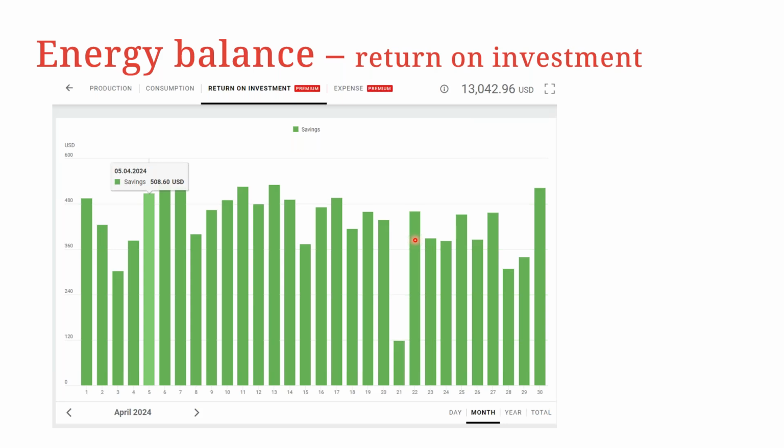And therefore, that's why it's very, very important to always bring your systems to SolarWeb, preferably for grid connected systems with a smart meter, because then a smart meter is able to tell you what is the overall consumption and gives this data to SolarWeb. Then SolarWeb is able to work out this kind of detailed data for you.